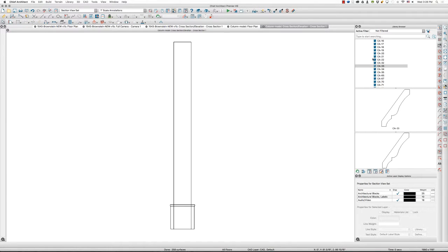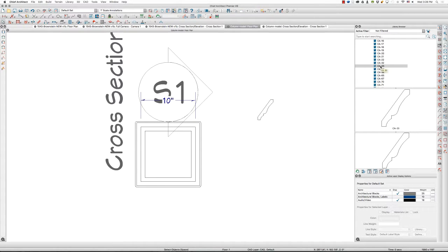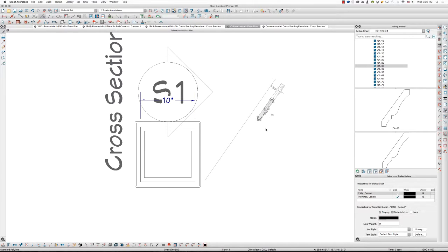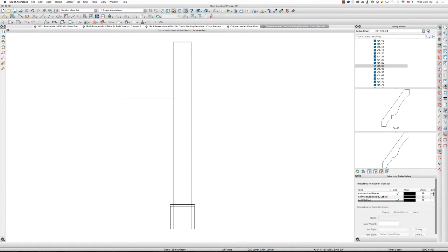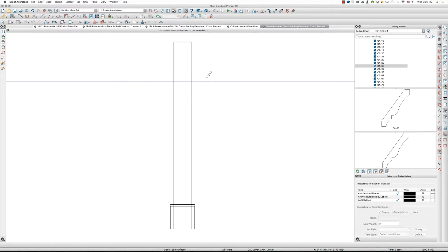I'm going to try it in section view. Last several versions don't allow this, and X9 is the same way. So you can place that molding profile, right click on that molding profile and place it in plan, and then I just grab that, and that's just a polyline. I'm going to copy it. Now I'll copy and paste it into my section.